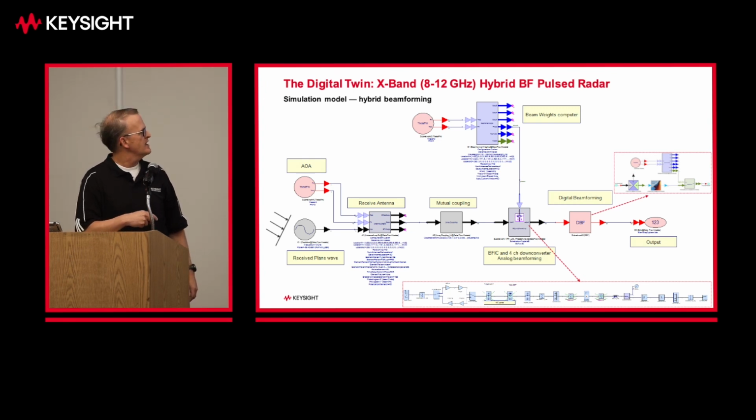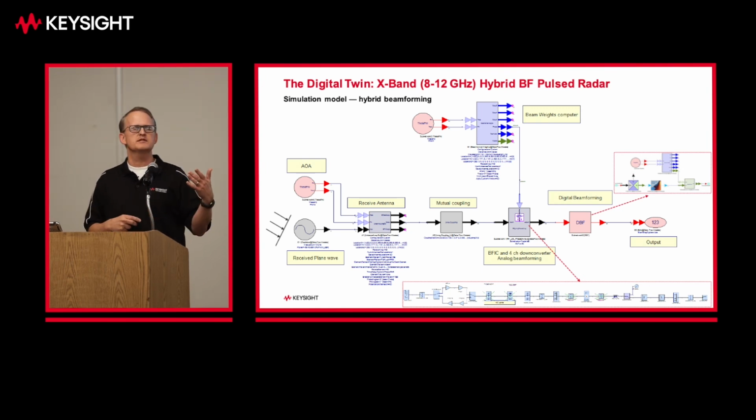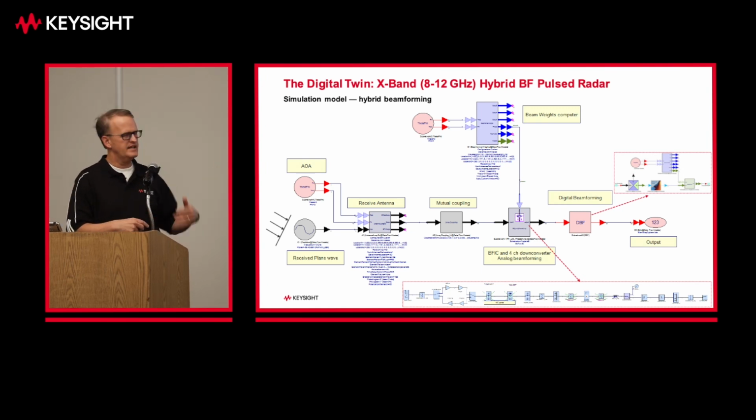And then this is a frequency domain subcircuit. The top level is a time domain simulation because we're looking at modulation and kinematic change. But basically, this is a subcircuit that if you push into it in SystemVue, it's a frequency domain simulation of our whole design. I'll show you that in a sec. SystemVue does the correlation and translates everything from the frequency domain into the time domain. You don't even have to worry about it, so there's no loss of workflow.